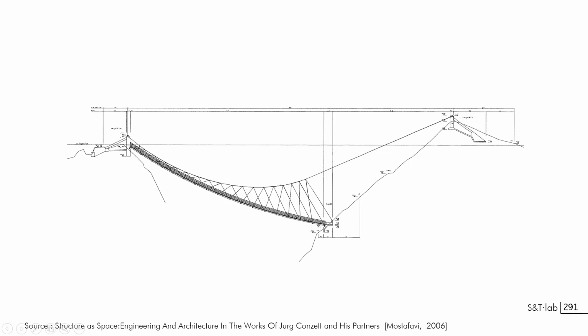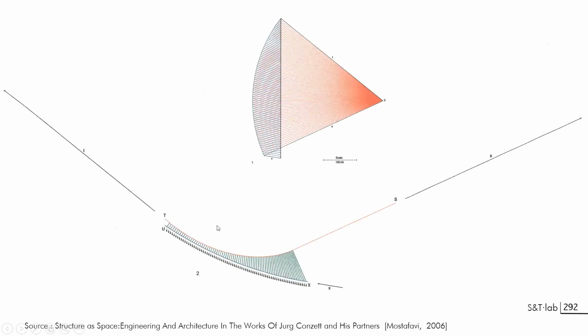You can find the first design of the geometry of this funicular hanging bridge was a funicular here, and you recognize the rays of the funicular polygon. At the end, you will see that you have a series of forces that will be applied here that will be equilibrated by 2 segments of the lower truss line and with the hanging arch here. And you can see indeed this closed cycle of forces in which we have the applied force about the direction of the hanging, and this hanging will be equilibrated by the support line.